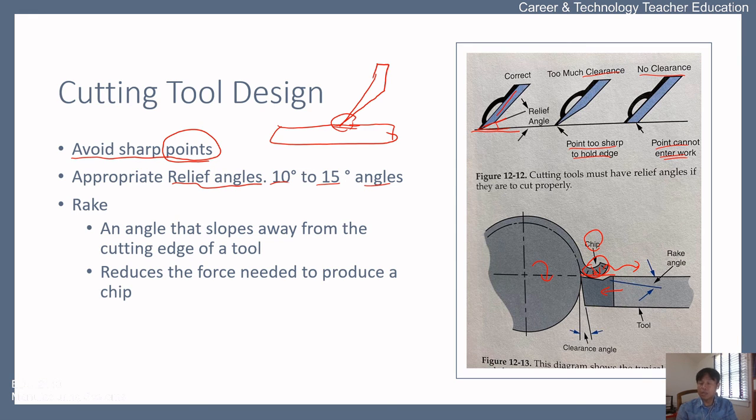In this example, I explained about temperature. If the angle, also the relief angle, is too much, there will be too much friction. That means friction increases the temperature of the tools and the material. This increase in temperature can melt the material, chips or tools, which could cause further damage.